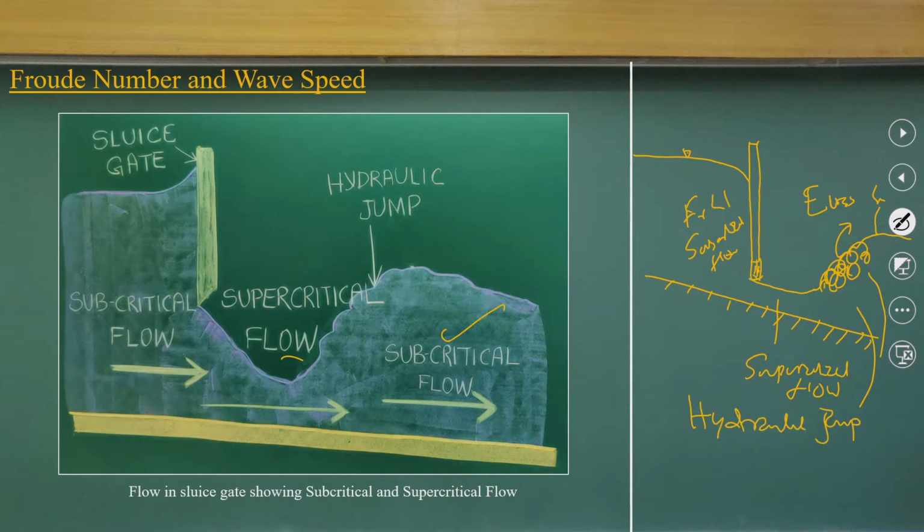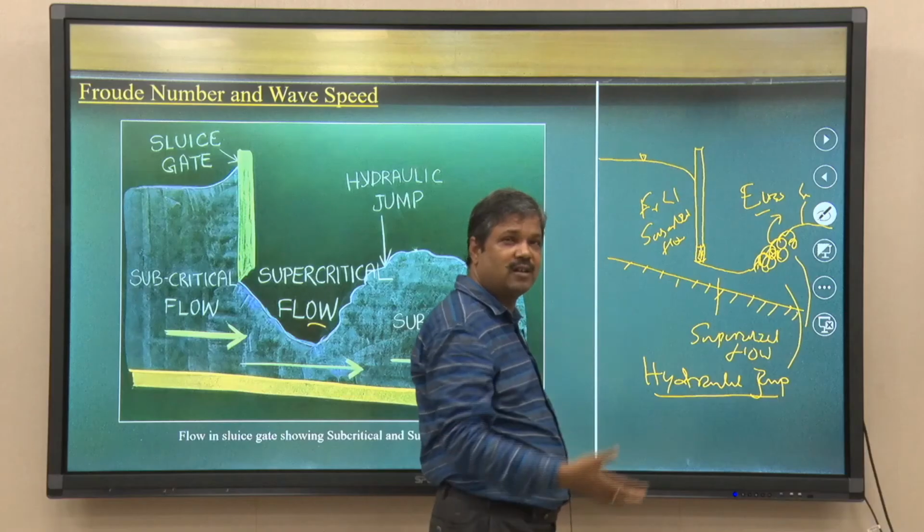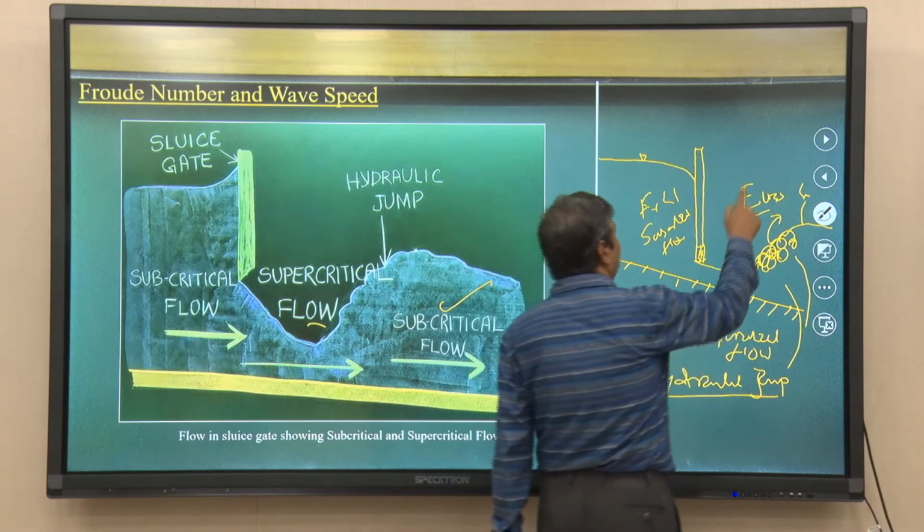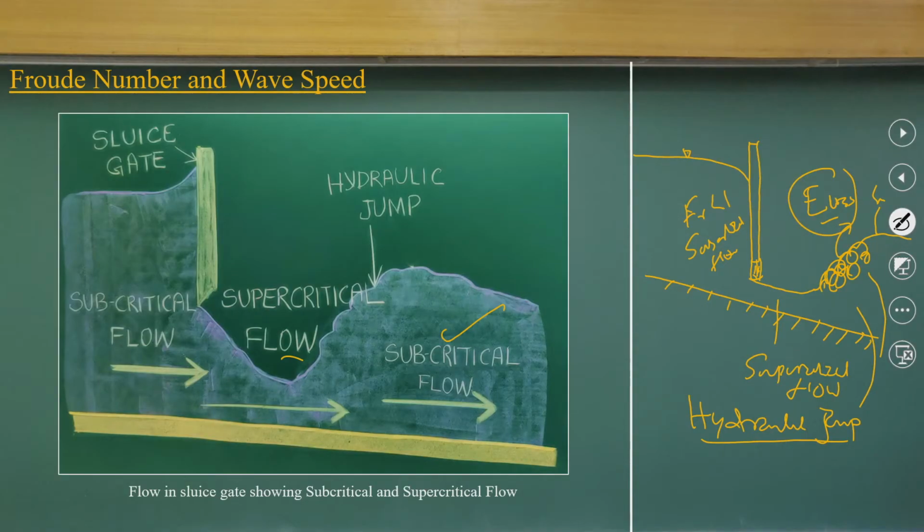and we try to design a hydraulic jump because at these hydraulic jumps the mixing process, the aeration process happens very dominantly. No doubt there is energy loss, which is required for some cases, but the hydraulic jump which is created from the supercritical flow to subcritical flow at the transition zones makes the sound noise and makes the turbulent structures. Because of that, you can have a significant energy loss, and in those regions jump formations are happening. That's the reason we define it as a hydraulic jump.